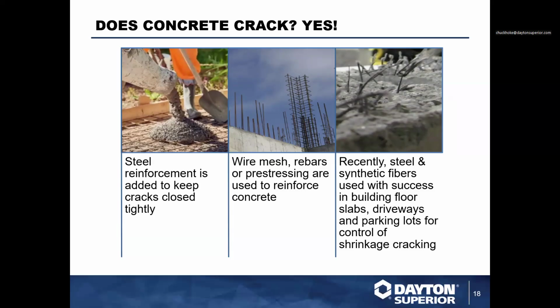What we are seeing today are new futuristic designs with admixtures, etc. But we've also changed from adding steel to the concrete mix to replacing it with fibers, either synthetic or steel fibers, as reinforcement. That's what's going to hold the slab together.